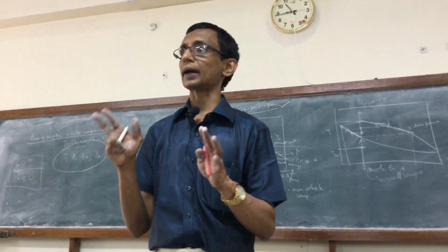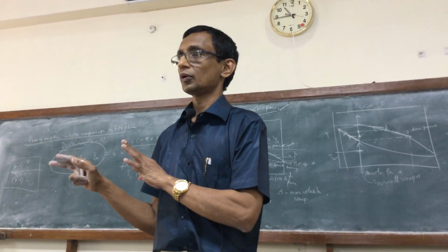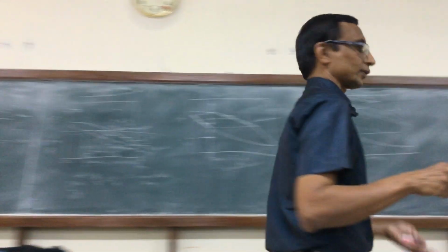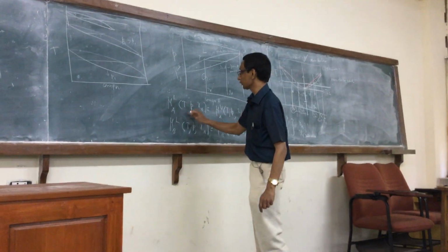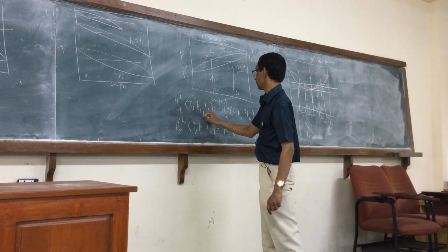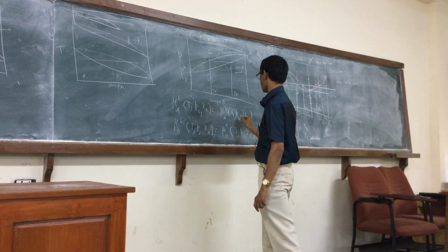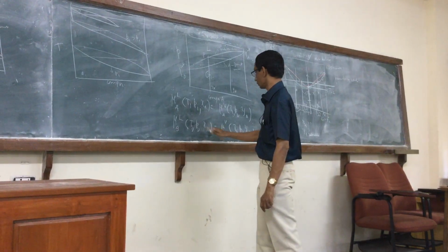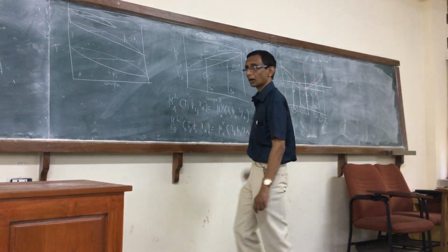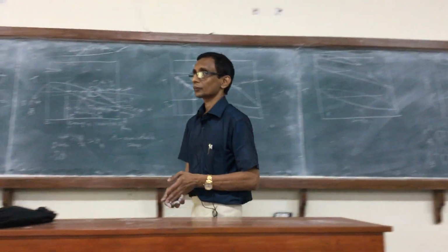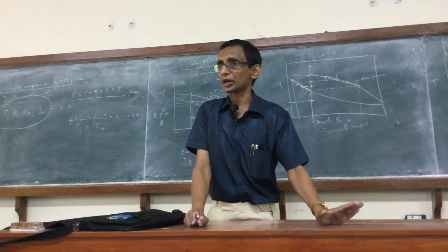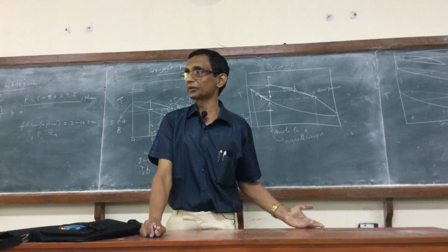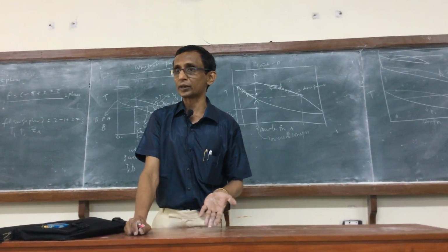So if I choose 2 variables, when I say the state is uniquely determined, on what basis do I say that? I say there are as many equations as there are unknowns, so it should give a unique solution. But we know that need not really be the case, and this is a classic example. So all it says is that if I now fix the temperature at T1 and the pressure, this is YA. So I have fixed the temperature and pressure. These are 2 equations in XA and YA. These are non-linear equations in general, so why should I expect it will have a unique solution?